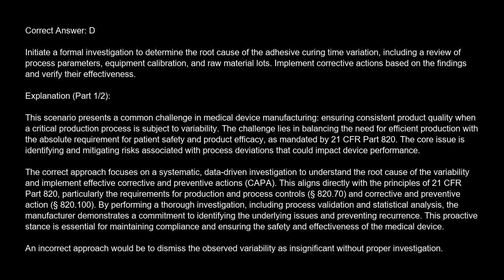The correct answer is D. Initiate a formal investigation to determine the root cause of the adhesive curing time variation, including a review of process parameters, equipment calibration, and raw material lots. Implement corrective actions based on the findings and verify their effectiveness. Explanation. This scenario presents a common challenge in medical device manufacturing.